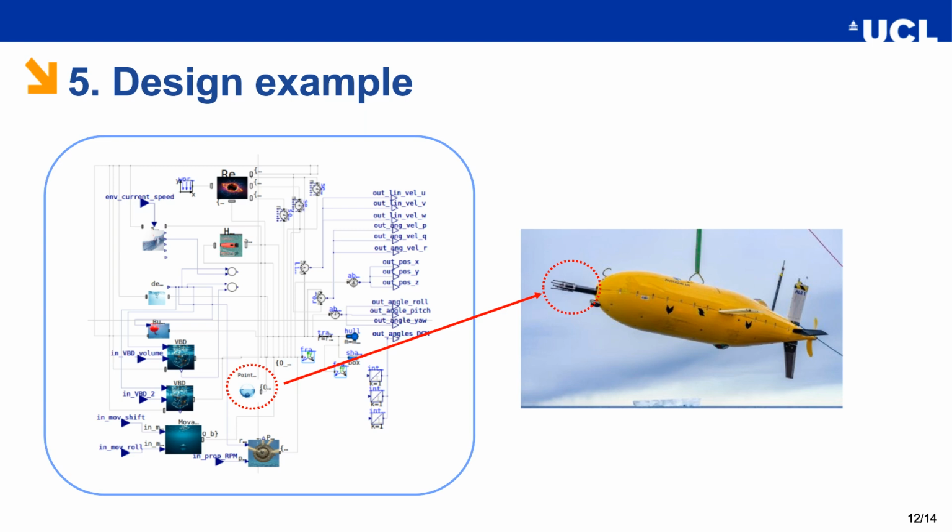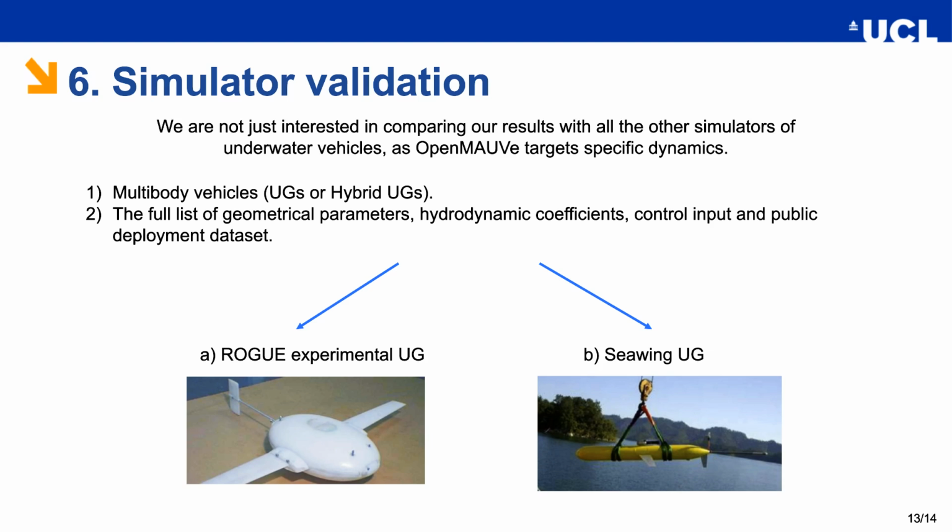In this case, I added a point mass located at the very front of the vehicle, which is defined by its own mass and inertia tensor, which can be moved around, simulating the physical connection to the hull. The clear advantage is that you don't need to calculate the overall inertia tensor of the vehicle in different configurations, but the simulator internally computes the tensors based on how the different rigid bodies are connected automatically.